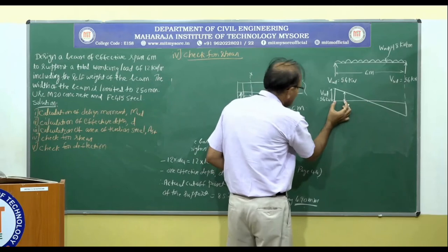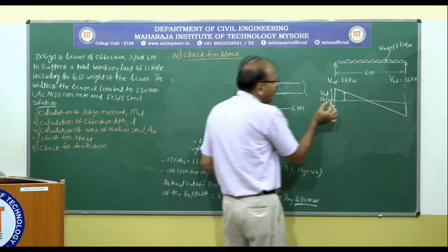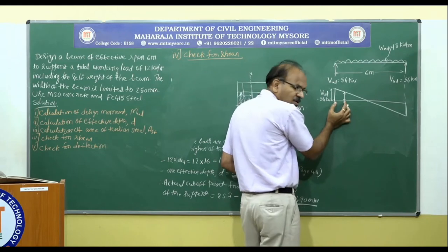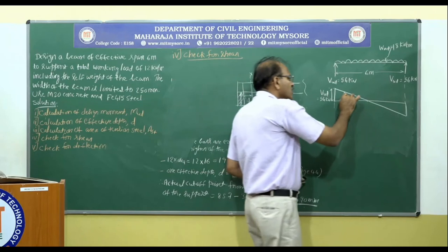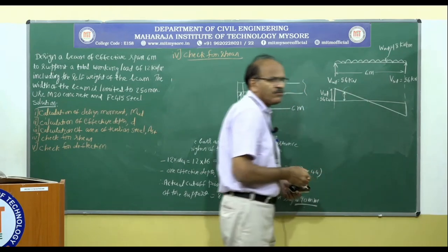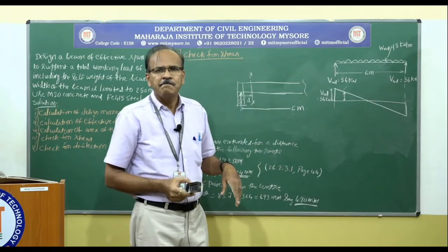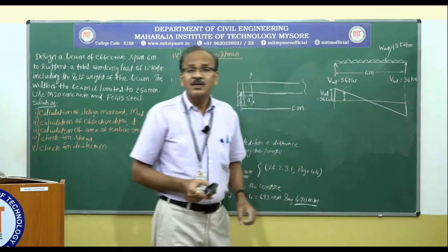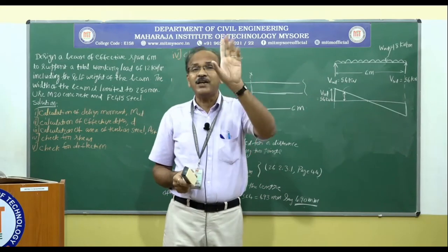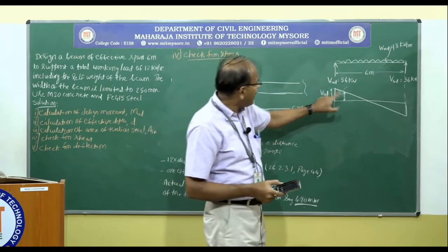That is at a distance of d plus half the width of the support is the distance. So there you can find out what is the shear force, that is the design shear force. Okay. So for this shear, you need to provide shear reinforcement, and this shear will be less than this shear.